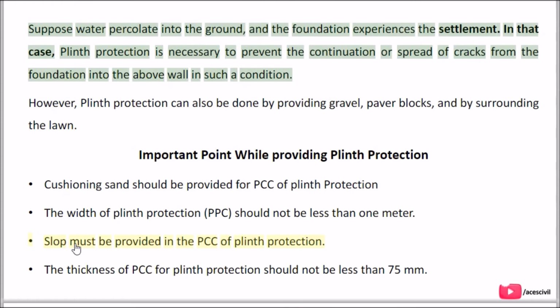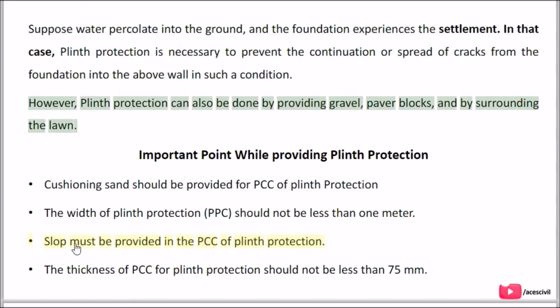Suppose water percolates into the ground, and the foundation experiences settlement. In that case, plinth protection is necessary to prevent the continuation or spread of cracks from the foundation into the above wall in such a condition. However, plinth protection can also be done by providing gravel, paver blocks, and by surrounding the lawn.